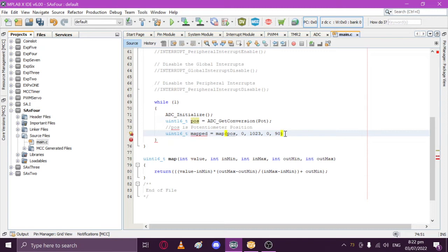Because as observed from previous attempts, the servo motor SG90 can have its pulse width at the value of 90, and it will correspond to a slightly greater than 90-degree angle.